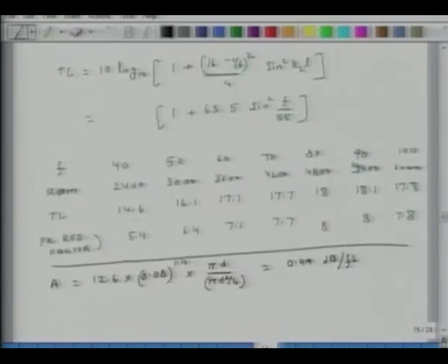So this is roughly 6 feet. So total absorption attenuation will be of how much? 3 dB attenuation. So over 6 feet there will be 3 dB attenuation by absorption. So the point being that absorptive mufflers are not that efficient.